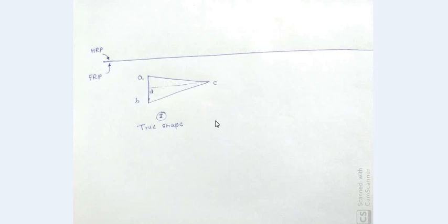Okay, so this isosceles triangle would be drawn in horizontal orientation. That's why the base is remaining free on the left hand side and this height appears in horizontal orientation. So this would be our first step, that is drawing the isosceles triangle in true shape with the specified or correct orientation: AB 40 mm, height DC 70 mm.